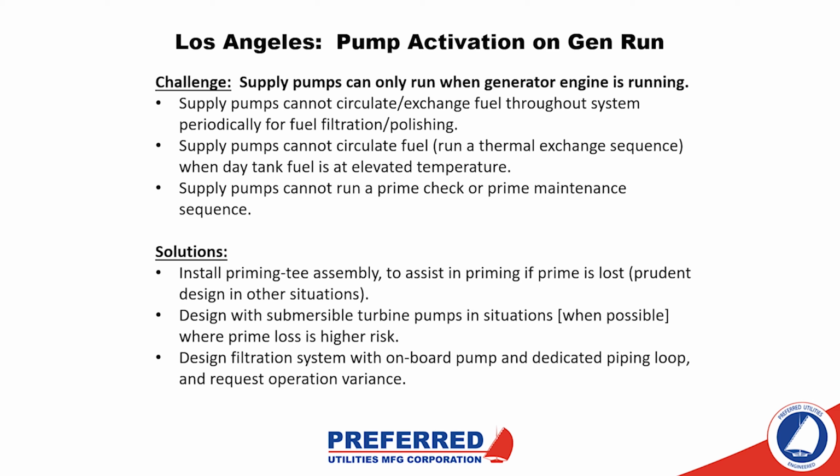So that's pretty inconvenient when we want to, for example, periodically turn over the fuel in the day tanks with the fuel in the bulk storage tanks in order to get that fuel polished. That day tank fuel is basically going to remain in the day tanks until the generator burns it. We'd rather exchange that fuel and get it polished.